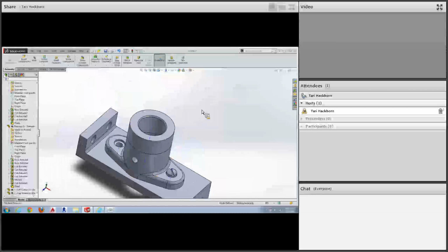Okay, for the second screw, they're going to apply that mate. Still hard for me to get used to calling them mates. They're going to apply that mate as you drag the screw into your assembly file.